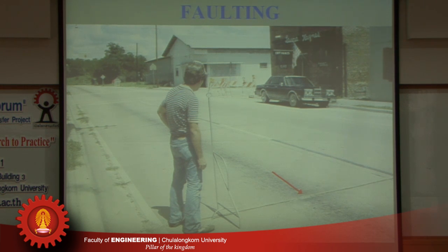Faulting is the difference in elevation at the joint. If you have faulting, when you drive over the joint, you feel a bump, and that's a form of distress.